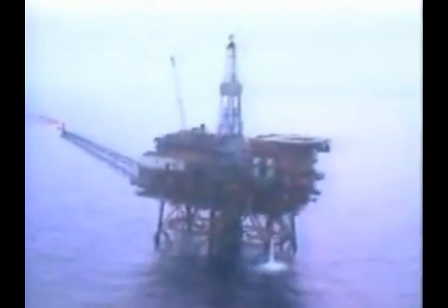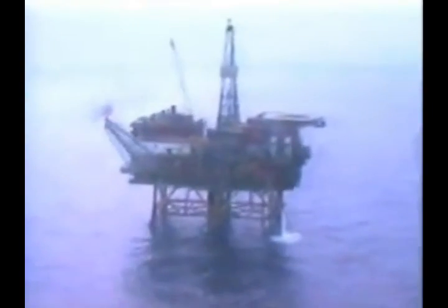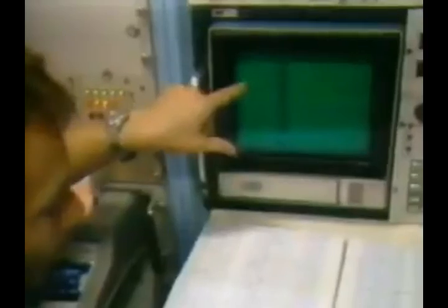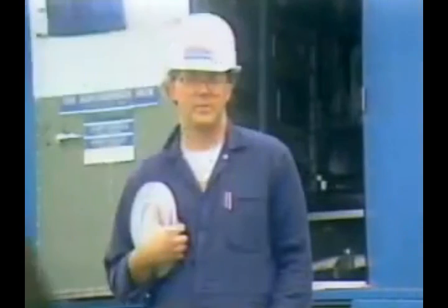Be certain to flow the well for sufficient time to flush debris from the perforation tunnels. Insist on good depth control techniques and carefully document all perforating activities. Choose a perforating company with a good record of quality control and safe operating practices.